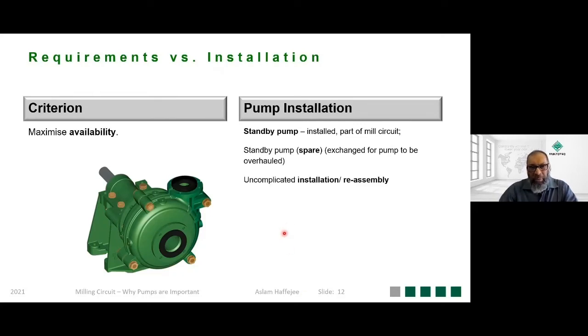The important thing about having your standby pump, which is just sitting outside or in your stores, is to have a very uncomplicated installation or reassembly. You don't want to have too many holding down bolts, for example. You don't want to have too much trouble taking out the existing pump to replace it with the replacement pump. So you've got to take all that into consideration.